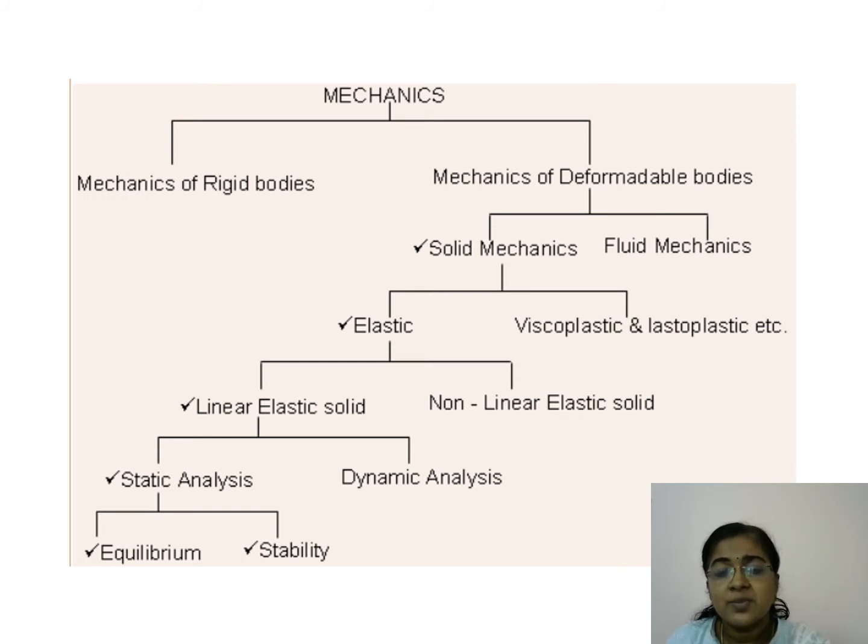Then the analysis may be either static analysis or dynamic analysis. In the case of dynamic analysis, we need to consider the variation of the load as well as the response with respect to time. But in the static analysis, the loads as well as response variation with the time is not considered. We will deal with the static analysis of structures alone in mechanics of solids. We have to consider equilibrium as well as stability considerations.